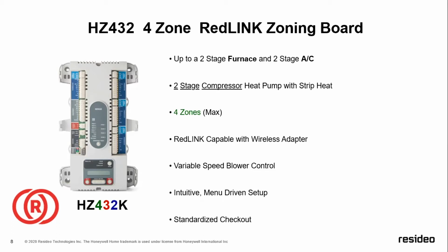So that I don't forget to talk about the variable speed blower control. Perhaps many of you that have utilized our zoning systems for a number of years may have noticed, where the equipment connections are made, that there is a DSBK terminal there. Well, what this allows you to do is, if you've got a single stage compressor operation, but you are utilizing a variable speed air handler,